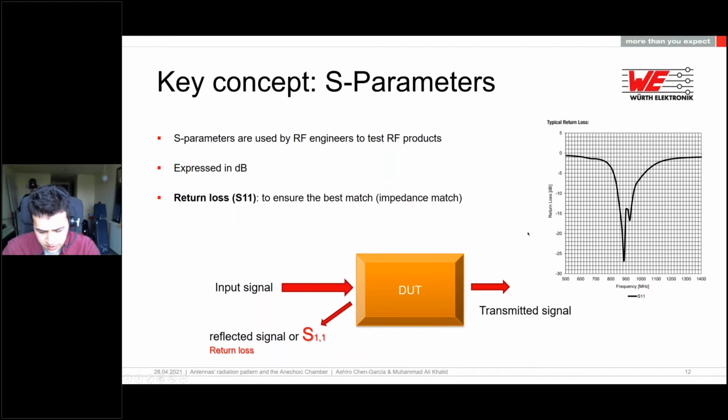As I said, for the antennas, which are single-ended components, we measure the return loss to check the antenna mismatch. A large mismatch produces a large S11, and a very low S11 at our desired frequency band almost guarantees the perfect operation of the antenna. I said low because it's a negative value. I would also like to say that the S parameters are available on our website to be downloaded.